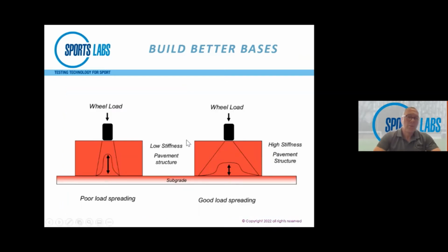We're looking at essentially load spreading. You can see a couple of graphics here where, depending on the type of material that's superimposed over the subgrade, being your soils, you're looking to create a stiff beam of material which doesn't flex, doesn't settle, is permeable, and gives good load spreading.